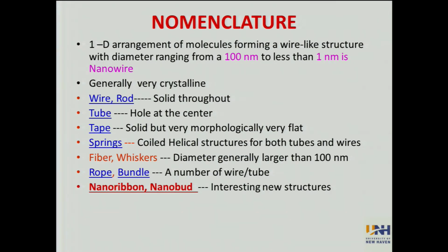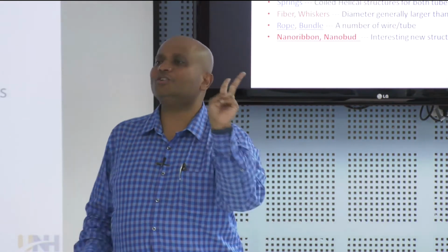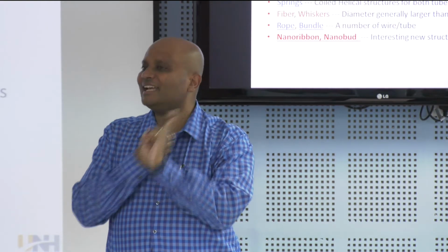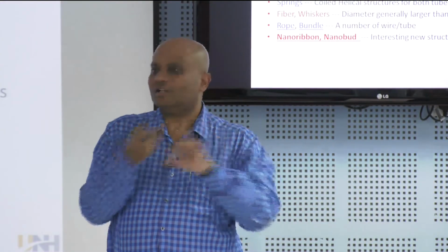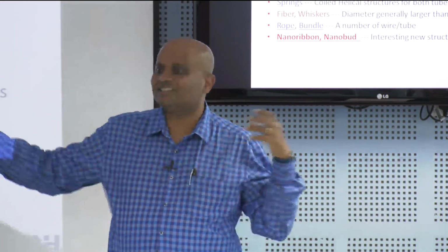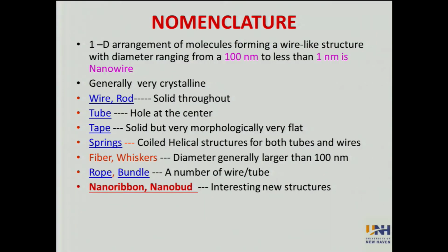Nanowire. Normally, if you have metals, for example copper, gold and all, they have the nano wire form. Nanotube is only carbon and boron nitride. These are the two. Boron nitride is a ceramic. So, these are the only two materials known to have a tube. Everything else is normally a nano wire. Silicon is nano wire, germanium is nano wire, aluminum is nano wire, everything else is normally a nano wire. Zinc, and then there are a couple which also form rods. This nomenclature is in general.